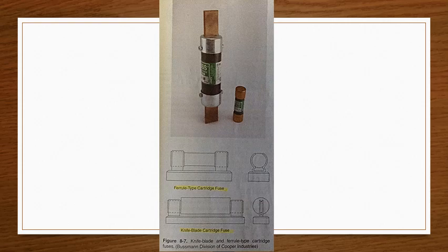Class H. These fuses can be renewable or non-renewable. The non-renewable types can be time delay. They have a low interrupting rating of only 10,000 amperes and are not current limiting. The low interrupting rating restricts their use in new construction.